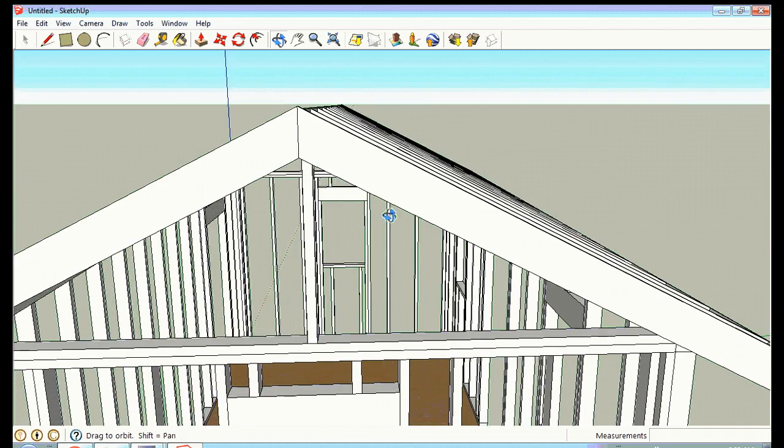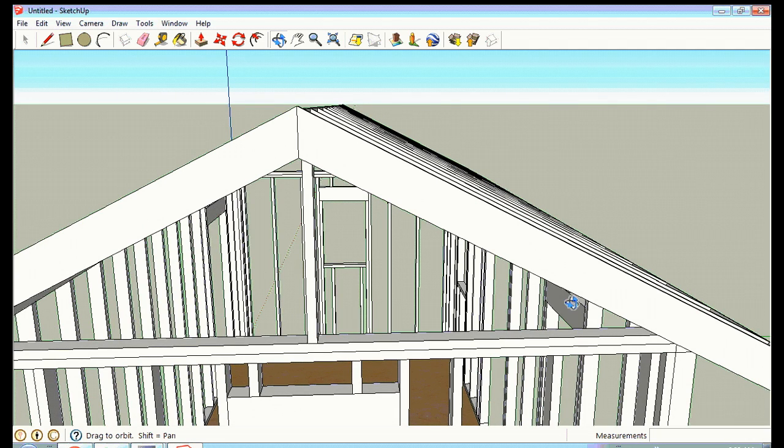Okay, then you're going to need to do some more end plates here so that we have something to nail this end wall to. You're going to need more support. So the easy way to do that is I just go on 16-inch centers. From the outside here, I'm just going to type over 16 inches to make a guide mark. Then using my pencil, I'm going to go over here 3 inches, or 3.5 inches for a 2x4. Make a mark, and I'm going to go in 1.5 inches.